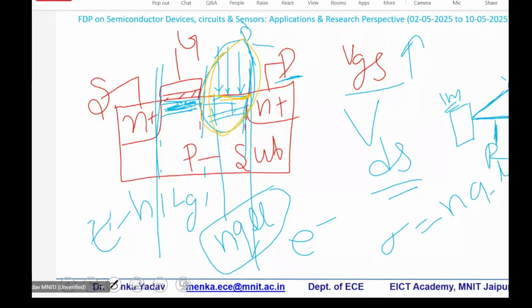So what you have to do is make sure that a very thin film of a transparent material is layered on top of this particular opening, so that the light can pass through that material and actually contribute to the electron hole pair generation in the wanted area.